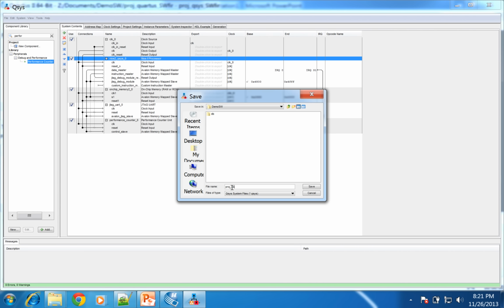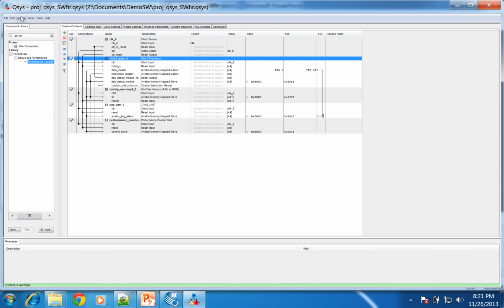Project Qsys. If you remember, we gave the same name to the top design entity while we created the project in Quartus. This is because when we generate our system in Qsys, it will give a bunch of files, and one of them will be the top file, with a top module, and that top module name will be this. As we'll be using the same top module for our whole design, I gave the same name to the top module of the Quartus project. Save it. It's good to go, so we can generate the system.